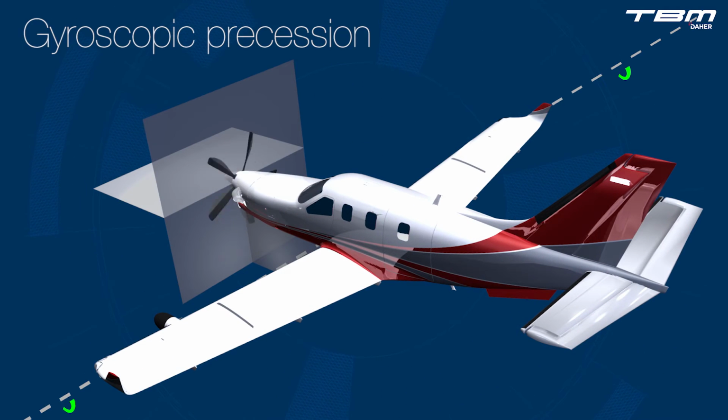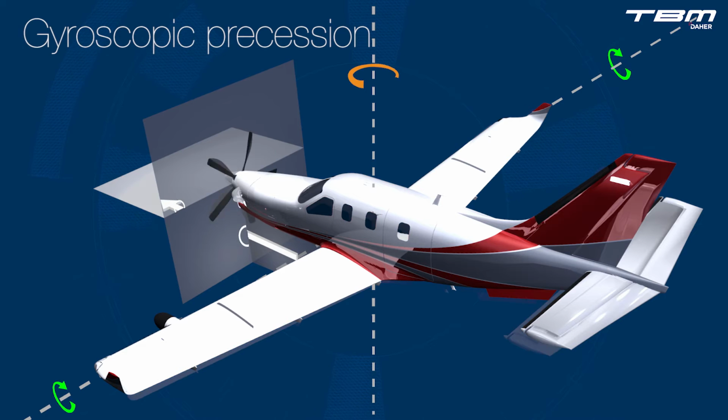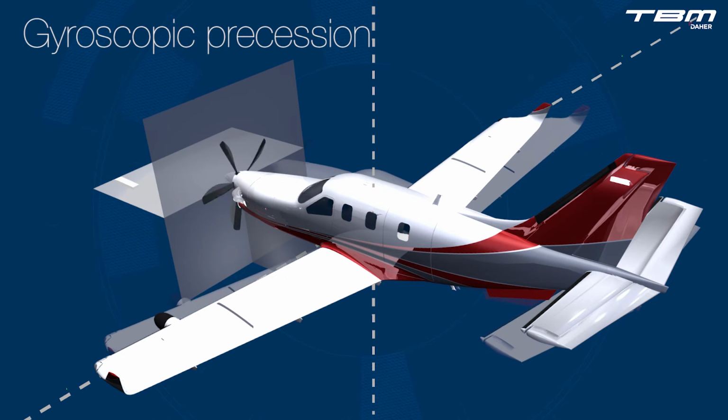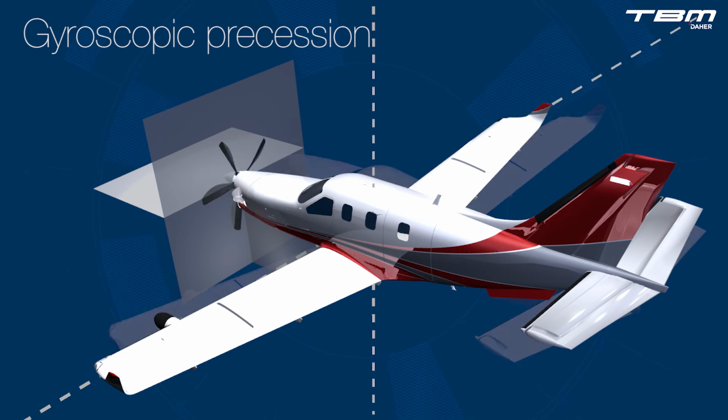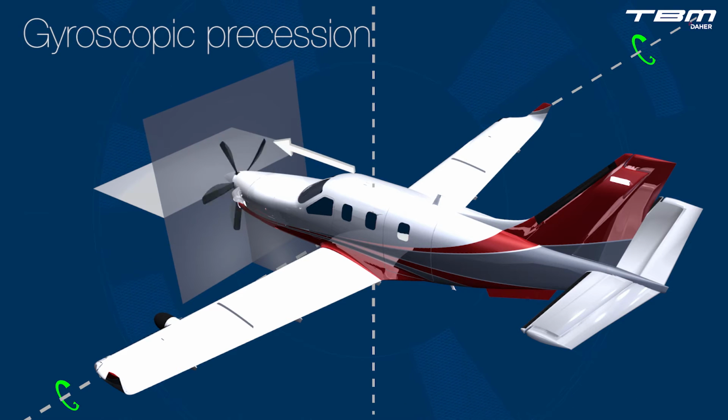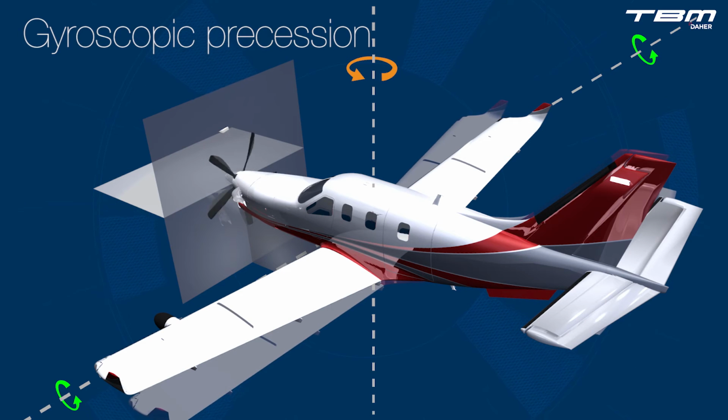Aggressive pitch-up transitions, as in a rapid rotation at takeoff, create a nose-right turning tendency: gyroscopic precession. The same is true with aggressive pitch-down transitions, as with a brisk stall recovery, but the turning tendency would be to the left. The effect is also more pronounced at low airspeeds.